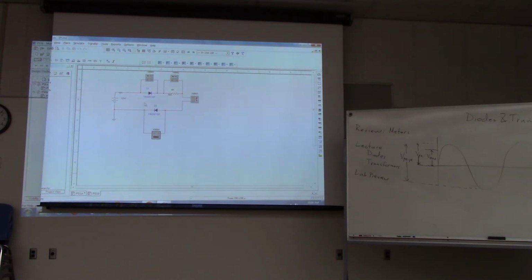So now when you look at this circuit, you're going to take out two diode voltage drops when you're analyzing the circuit. You would start off with 12 volts and then subtract about 0.6 volts twice, so about 1.2 volts. So you should be left with about 10.8 volts across this resistor, and then you could use that to calculate your current.